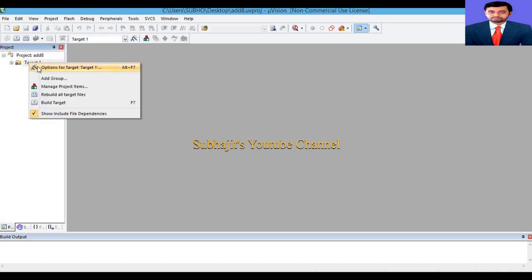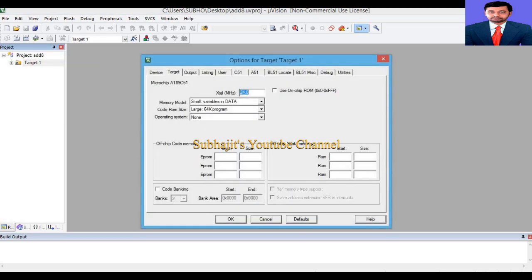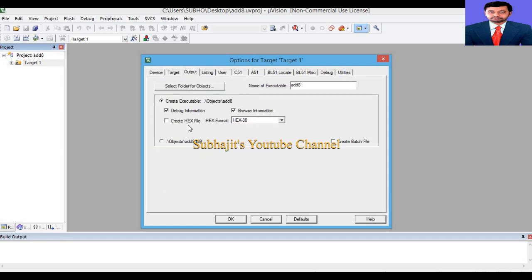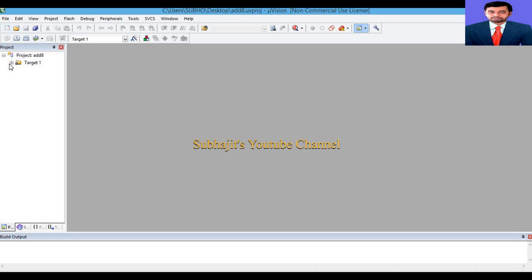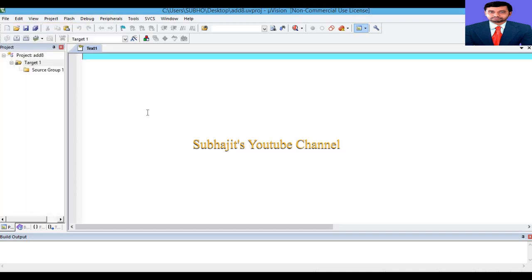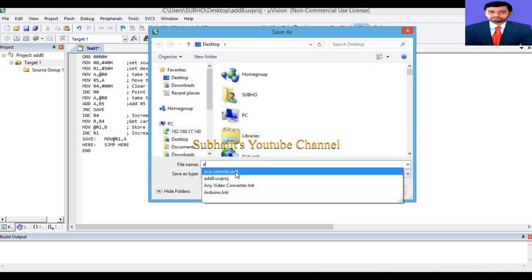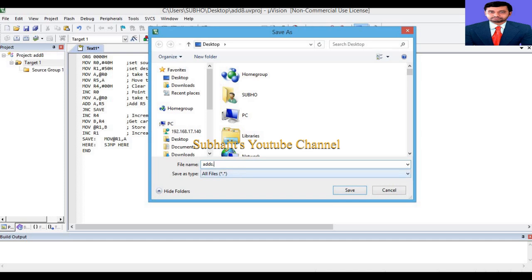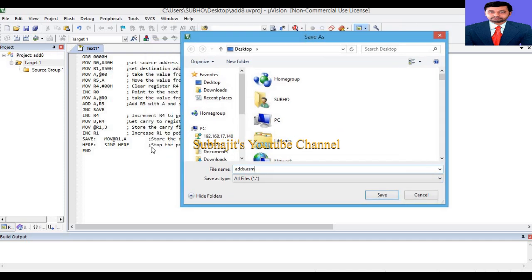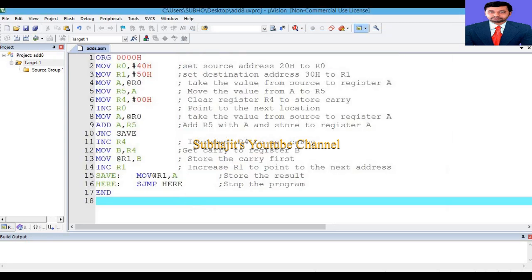Next go to the target, go for options, select the frequency, select the output file, create hex file. Then go to file, new, paste the program, save the program with a name, again with the extension of .asm, mandatorily. After saving the program you can see the color of the program will change.